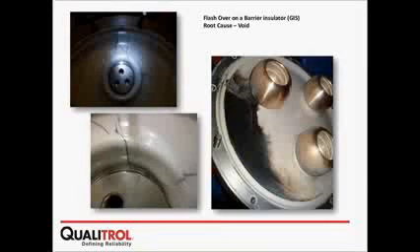If the protection doesn't open after the failure, it can get even worse. In a partial discharge, the pressure will increase, and the rupture disk will blow up. And it will blow up with hot gas coming out from that. With the hot gas coming out, if you have a person walking beside that, they can get serious injury.